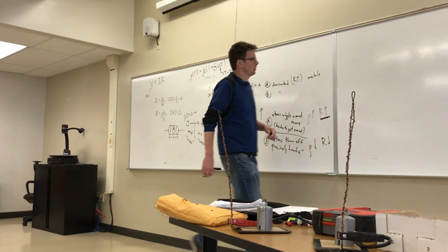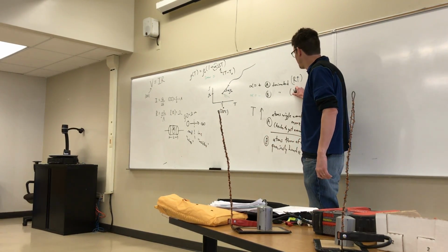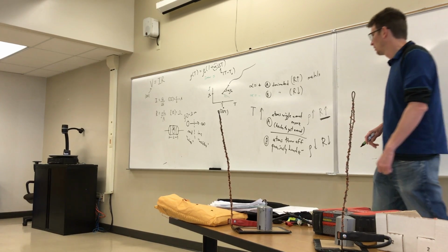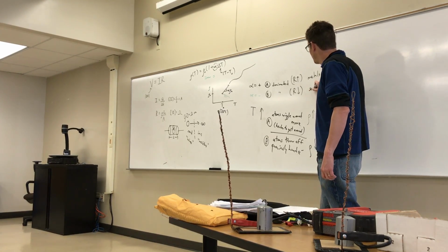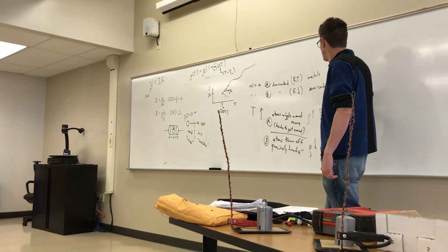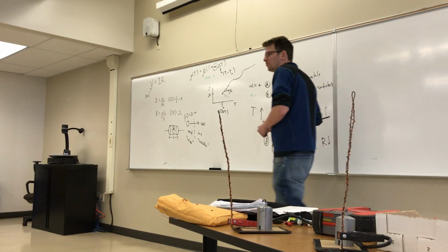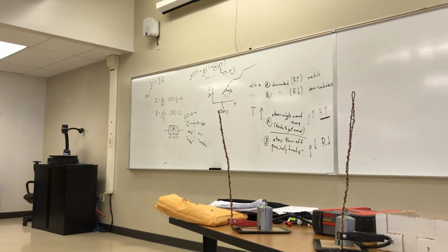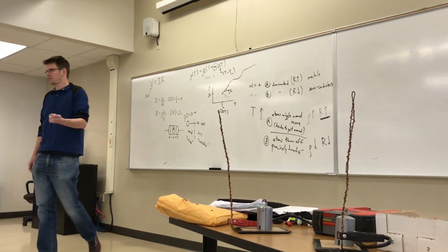The ones that have negative temperature coefficients, where the resistance actually decreases with temperature, that's an important class of materials called semiconductors. So these are things which don't really like to have electrical flow happen, but if you increase the temperature, you can actually encourage the flow, whereas before the resistance was higher, you're increasing the temperature and it's lowering the resistance.